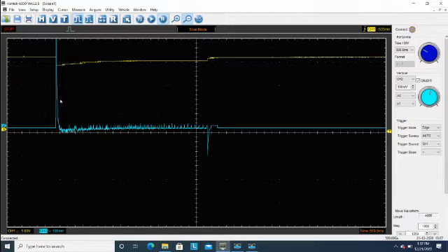When we turn our electric motor off, we are stopping current flow to that electric motor. We're opening the circuit. And therefore we see our voltage go back up to our 16 volts. But notice what also happens at that turnoff point. Notice that we see current in the opposite direction. Well, the motor doesn't come to an instant stop. It coasts.